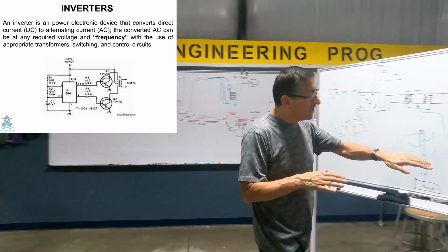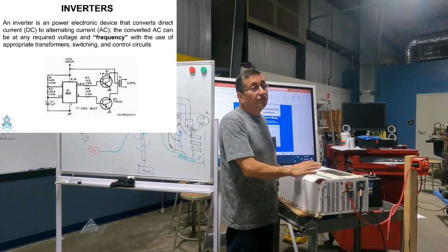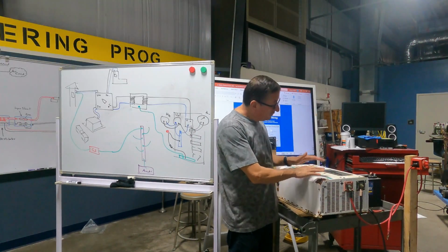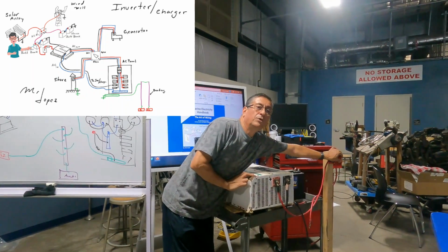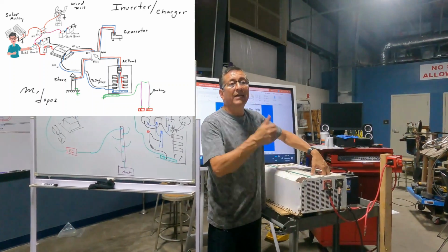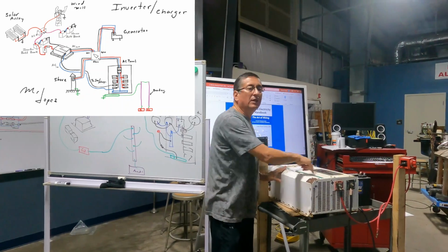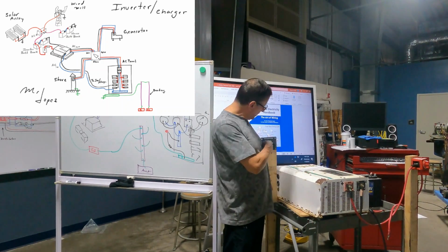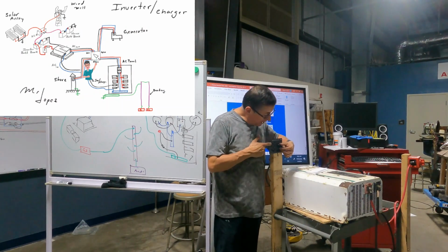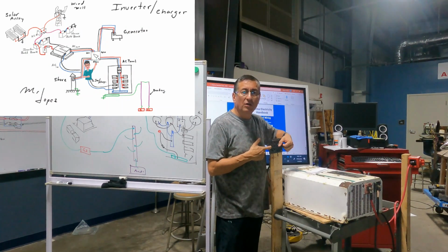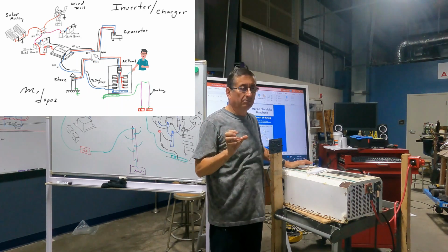The traditional inverter like this, this traditional inverter is not smart, it's not intelligent. This inverter receives DC power from the battery bank. I turn on the switch and the power enters here as DC. And this element converts it to AC when I turn on the switch. The AC power enters here in the switch selector: generator, shore power, or inverter. That's clear, guys? And this power enters the AC panel.